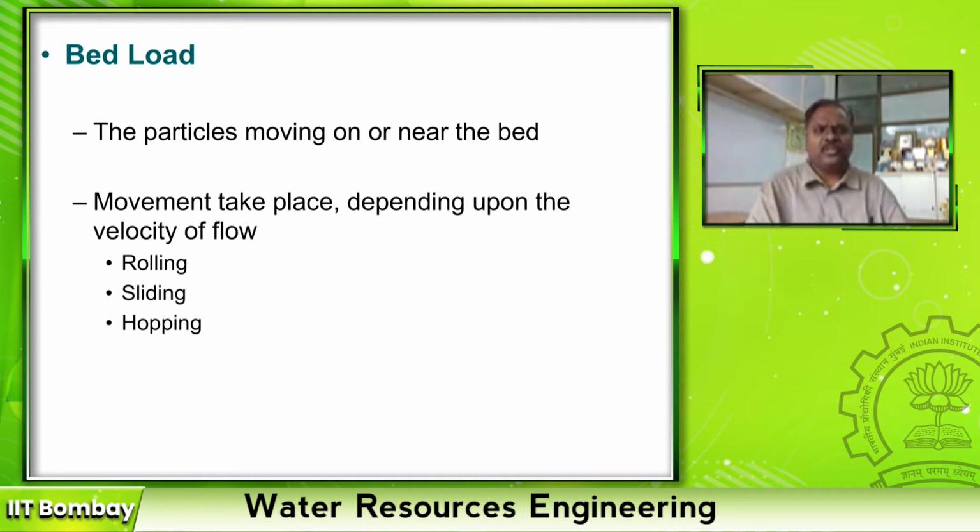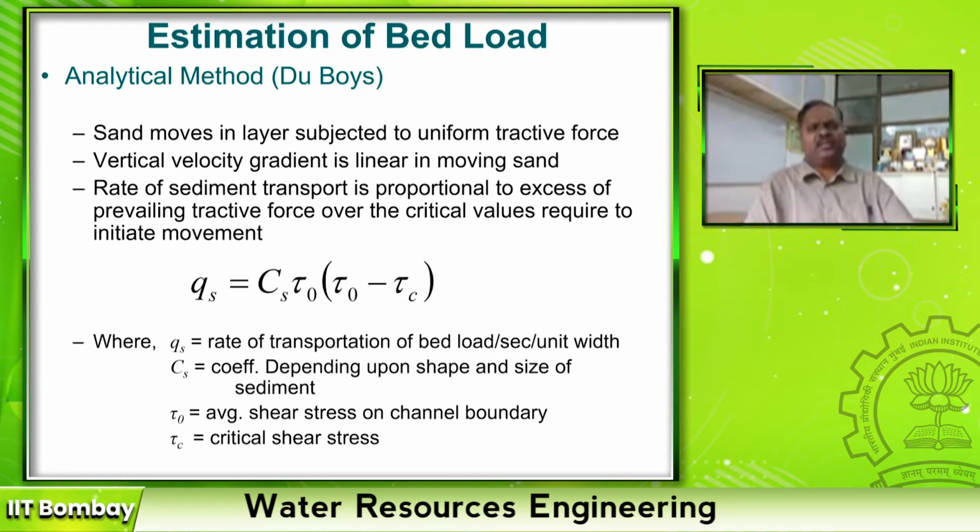The bed load. Now we will see one by one. The bed load is the particles which are moving on or near the bed. This depends upon the velocity of flow, which makes the sediments roll, slide and hop. There are certain analytical methods, right? The first method was Du Boys, right? Sand moves in layers subject to uniform tractive force, where this depends upon the shear stress as well as the bed load rate of transportation, right? Per second per unit weight.